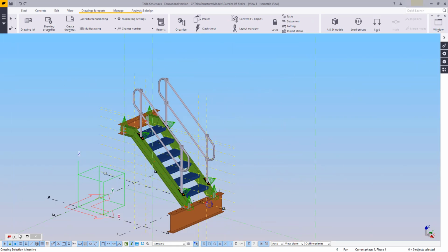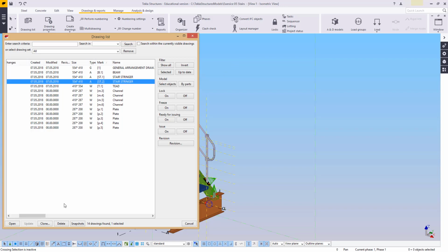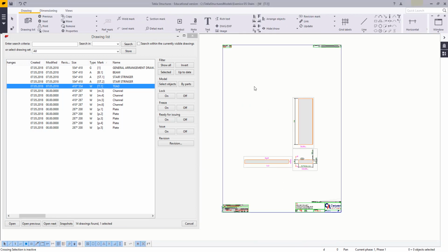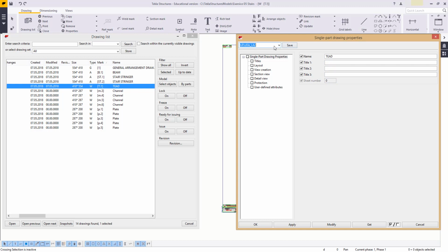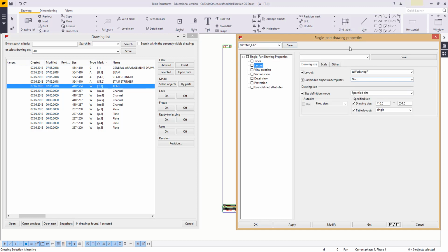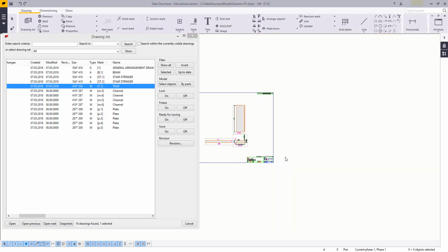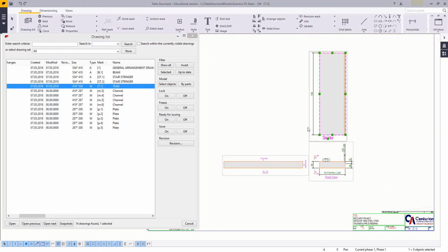And that should be it for the drawings. After this is done, I am going to, of course, do the stairs. And we will need to, it does say landscape, but obviously Tekla does not understand what landscape means. So let's just swap these two values around. Modify that. Does that. Wonderful, that's now landscape.